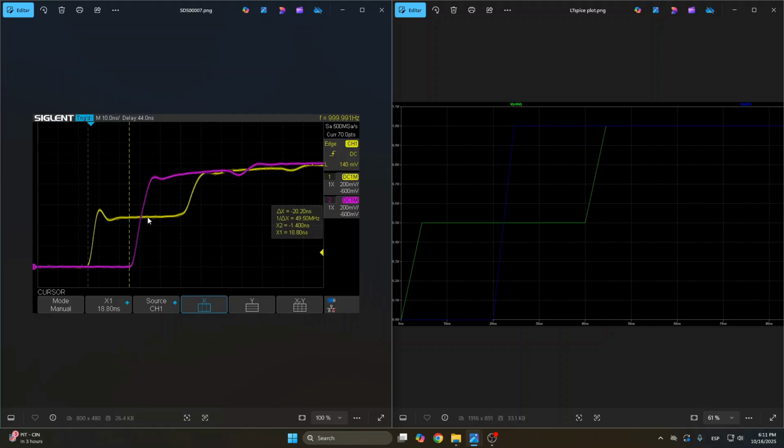So if the characteristic impedance was very different to 50 ohm, this voltage divider wouldn't produce exactly half the voltage of the input signal. We will have a different value, either lower or higher, depending on if the characteristic impedance was higher or lower.